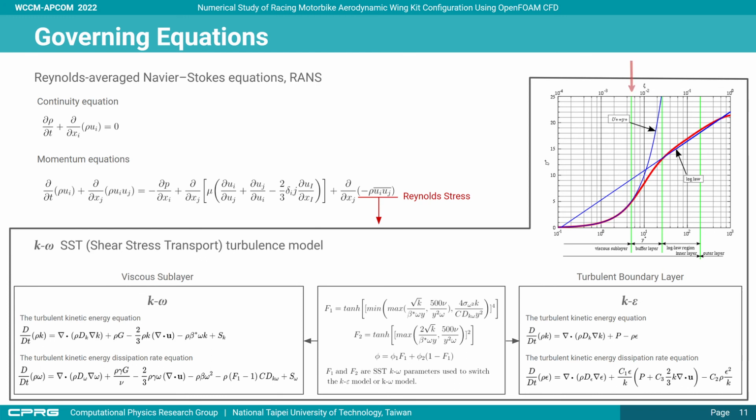We have to make sure the y plus value in each case must be under 5, and the lower the better. All the refinement level settings must follow this rule as well, even if the y plus value increased with higher inlet velocity.